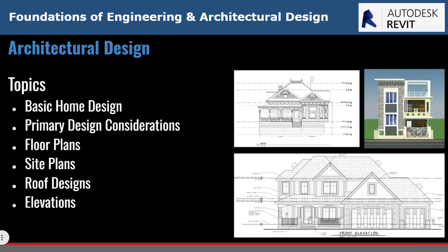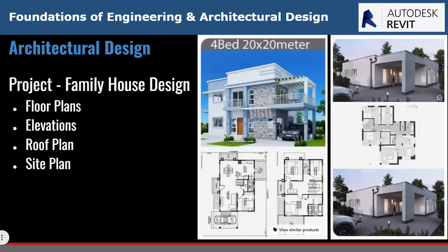We will do this project in Revit, which is 3D building modeling software. What's really nice about it is, for example, if you have your building and you move a wall over 3 feet, the program will coordinate that so it does that on the floor plans and on the elevations and any other plan where that window is seen. In AutoCAD, it won't do that. You have to go in and physically move each one in each of the drawings. So that's a nice advantage of Revit, that it coordinates it all and creates this 3D model of it. And you can take your drawings right from that.